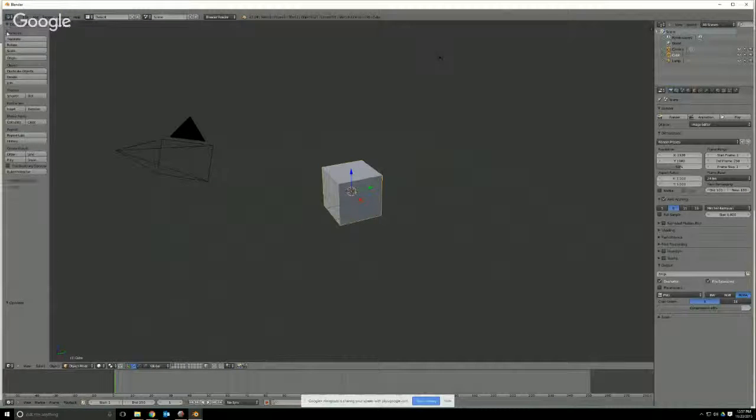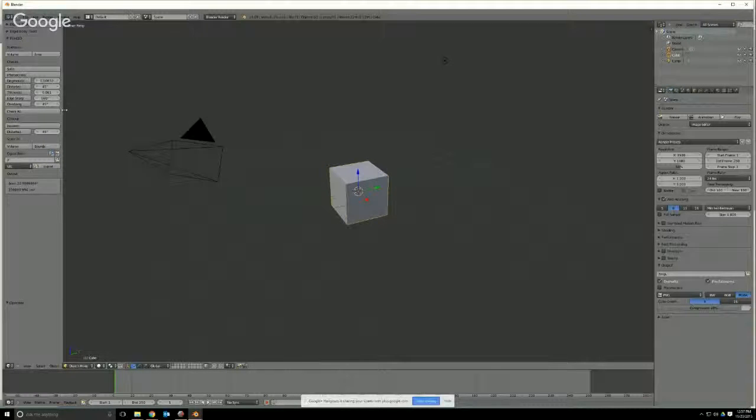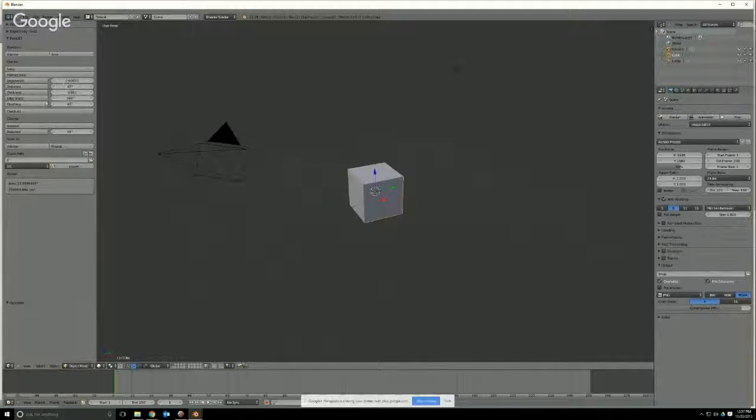There's the object tools, rigid body tools, but now there's Print 3D. What it does is it allows you to calculate the volume, calculate the area, do solid checks, intersections. We can expand this out a little bit. Do some thickness checking, all of that. It does have some not rudimentary tools.